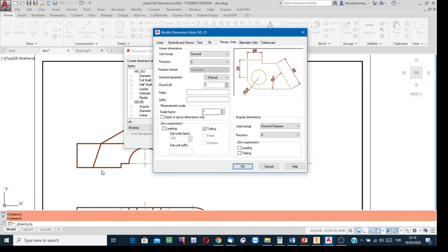Okay? So you drafted the projection using millimeter, and you're going to show the dimensions in millimeter. Then yes, keep this number as unity, 1. But in civil engineering, yes, you drafted obeying my recommendation, using millimeter for the projections. Why do I recommend this? Although it is possible to change the unit of measurement for the entire template from millimeter to centimeter, it is not recommended by me.